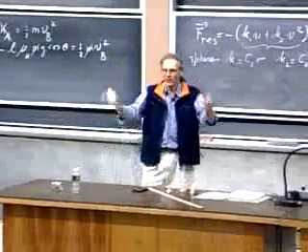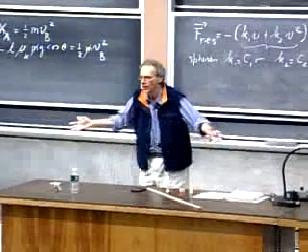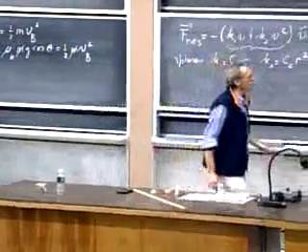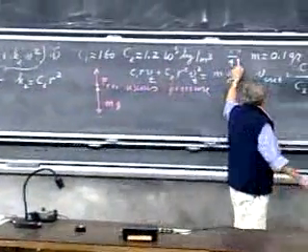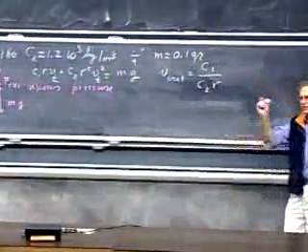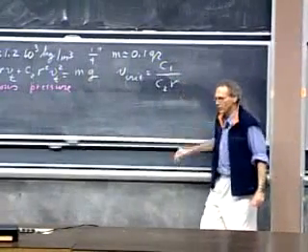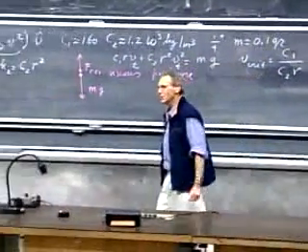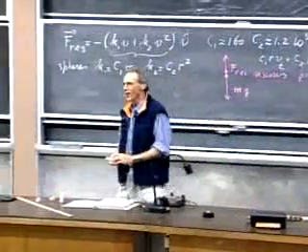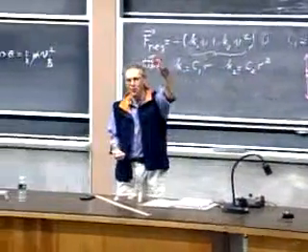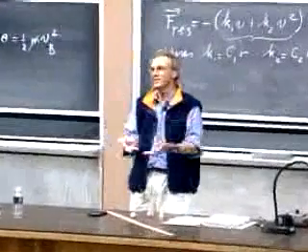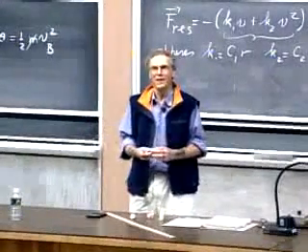It simply means that the two terms are equal. That's all it means, nothing else. If you calculate for a 1/4 inch diameter steel ball bearing, you can calculate r, you will find that the critical velocity is about 100 miles per hour. And we know very well there is no way when you drop a 1/4 inch ball bearing into this syrup that it's going to come anywhere near that.